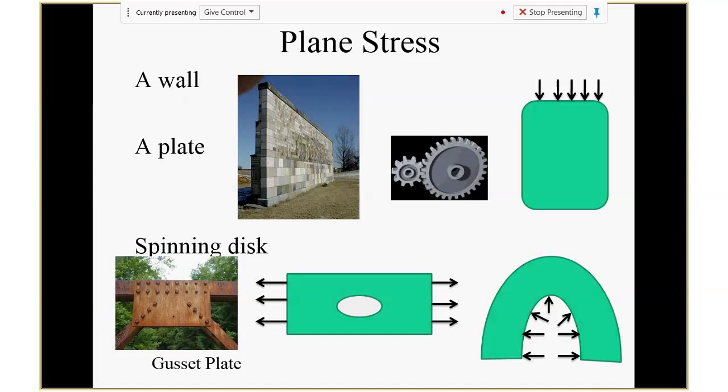everywhere in the z direction, as having no stress. Someone is pushing from the left or right side. In that situation, we call it plane stress. The most common situation for plane stress is a plate, a thin structure. The third dimension is really small, like a sheet. If you stretch this sheet, or pull or push on both sides, that's a perfect plane stress situation, with nothing across the thickness. So that's one.